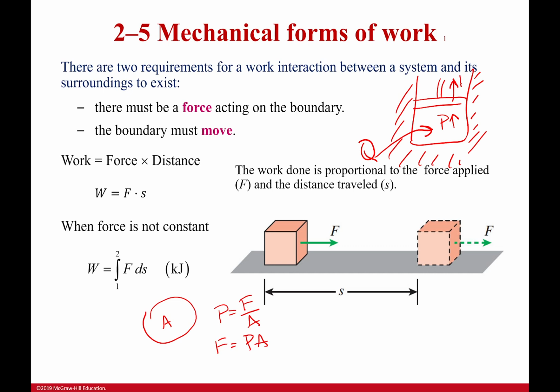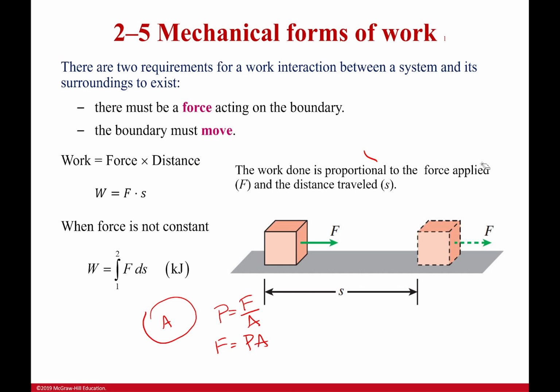Okay, now I've got a force. So I've got this force right here, and that's going to cause that piston head to move. How far will it move? Well, it'll probably move a distance s. And that means that the work that your gas just did in moving that piston head is going to be force times s. Wait a minute. Oh my goodness, we're back to the exact same equation. So while we will typically be talking about things in terms of pressure and volume, it's all coming back to that same simple thing. We're moving a boundary by applying a force. Where does the force come from? Pressure in this case. But we're still just moving that boundary.